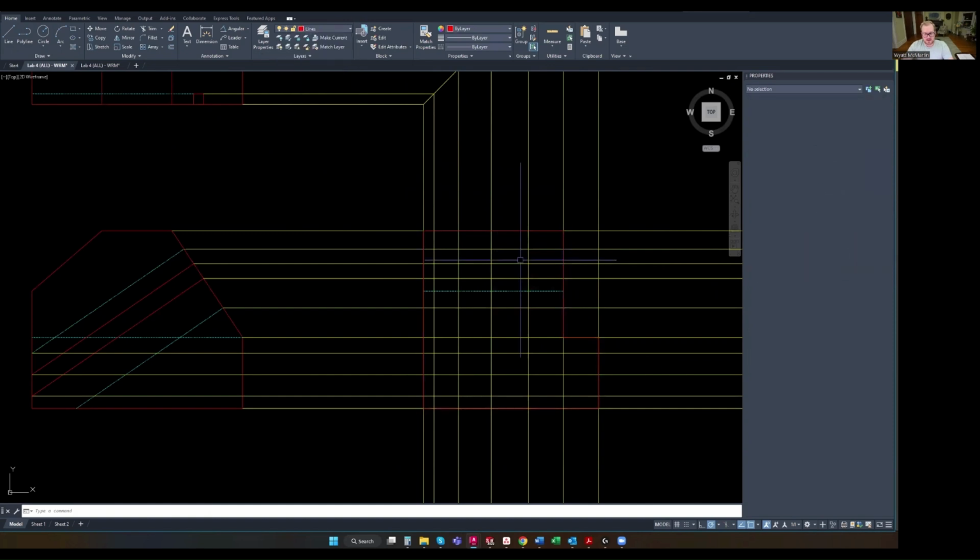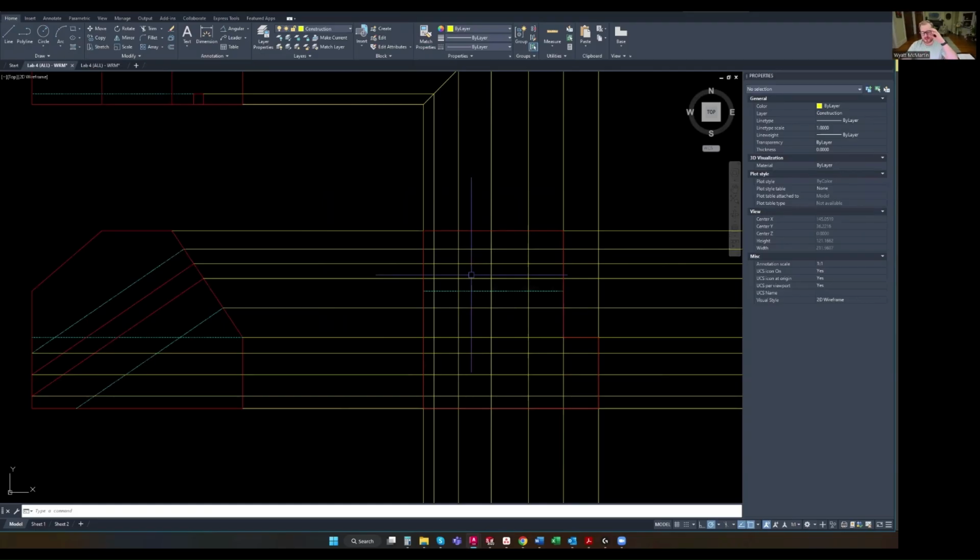That is okay, as long as I go ahead and select my construction lines here and turn those to the lines layer. If that got really confusing for you, if you were still on construction lines when you created that line, just click escape, click out of it, go ahead and change your layer to the lines layer, and then you can go ahead and do it again.